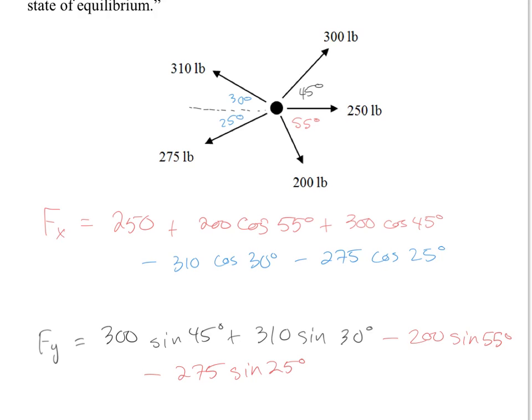Now, the other part we're going to see with structures is shear stress and how it works. Imagine here's a pin, and there's a plate coming off the pin this way, and another plate attached this way, and they're pulling against each other. It could cause the bolts to snap. They're not both pulling from the same location. Even if these forces are equal and opposite, if this one is pulling here and this one is pulling here, they're both causing shear stress. So the bolt itself could snap like this.